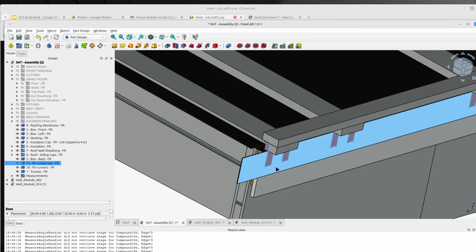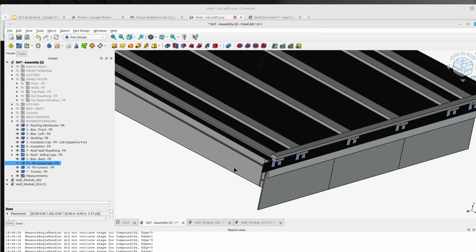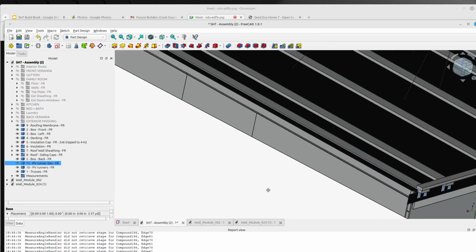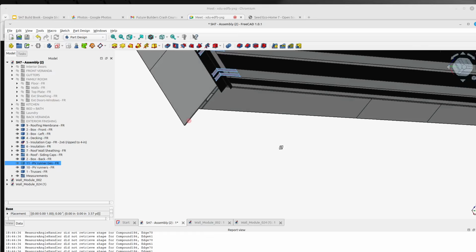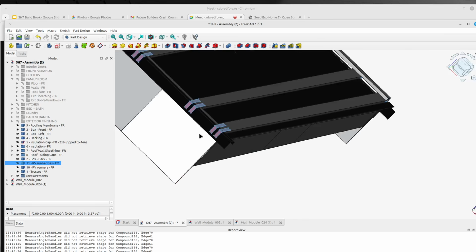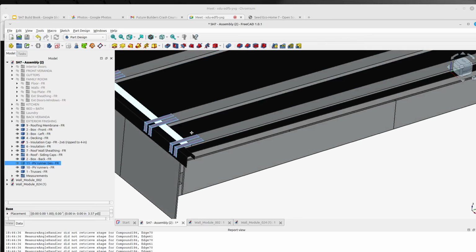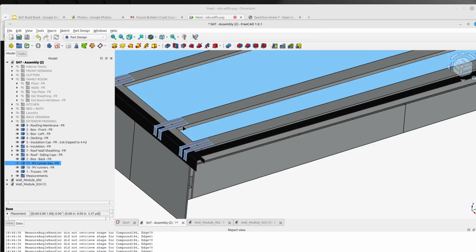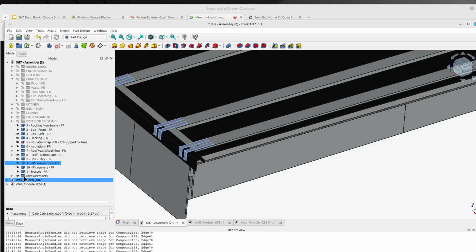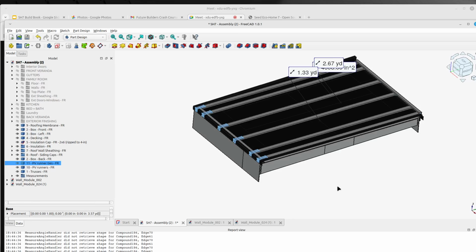So we use some roof mastic to seal up those holes, and butyl tape and roof mastic to seal up any of those holes. Same through that's the front side. The nails that go into the PV runners, they are 1.5-inch nails. There's no penetrations at all in the roof membrane, and that's pretty much the assembly explanation for the roof.